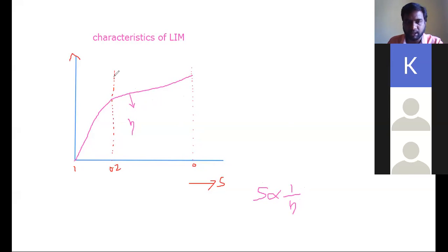Next, we are going to discuss the power factor. The plot will go like this. This is the plot for power factor. Initially, the power factor is high when slip is 0.2. When slip is nearly coming to 0, the power factor is also reduced. Why are we considering this power factor? When the power factor is reduced, what happens to the performance of the machine?